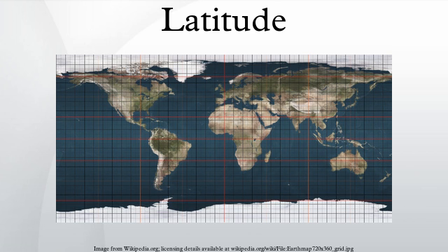Geocentric latitude. The geocentric latitude is the angle between the equatorial plane and the radius from the center to a point on the surface. The relation between the geocentric latitude and the geodetic latitude is derived in the above references as follows. The geodetic and geocentric latitudes are equal at the equator and poles. The value of the squared eccentricity is approximately 0.0067 and the maximum difference of φ − ψ is approximately 11.5 minutes of arc at a geodetic latitude of approximately 45°5′.